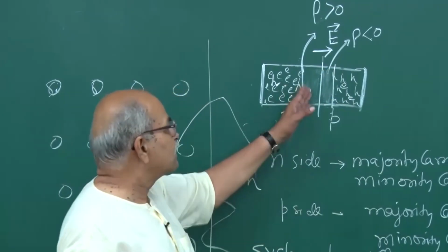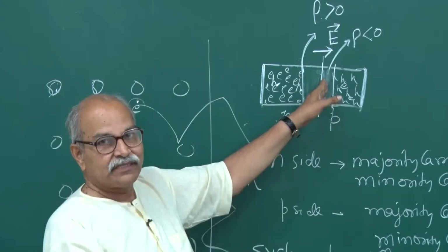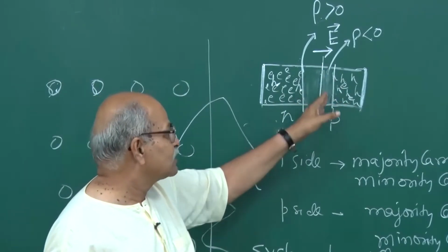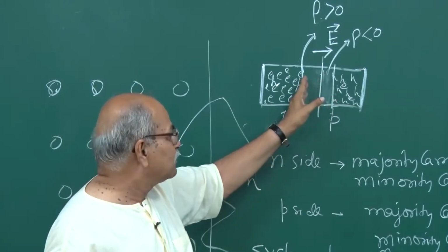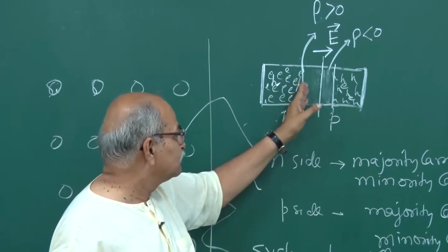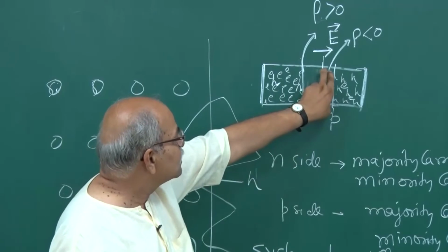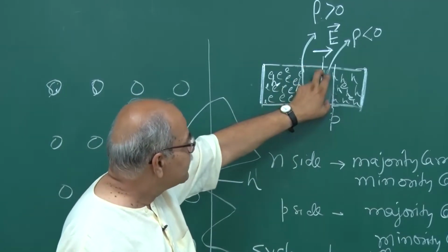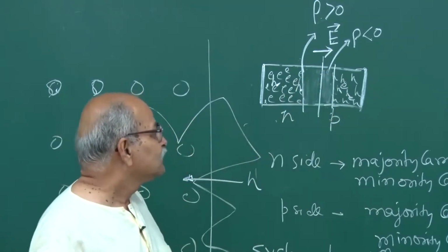The electrons which are diffusing to the right, because of the large hole density there, are trapped, and then if there are holes left, more electrons will come, and this width will be adjustable. As many holes are here, that many electrons will go from this side and fill, and both ways, from this side to that side, that side to this side.